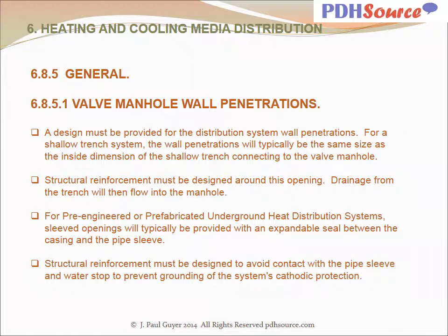With regard to valve manhole wall penetrations, a design must be provided for the distribution system wall penetrations. For a shallow trench system, the wall penetrations will typically be the same size as the inside dimension of the shallow trench connecting to the valve manhole. Structural reinforcement must be designed around this opening. Drainage from the trench will then flow into the manhole.